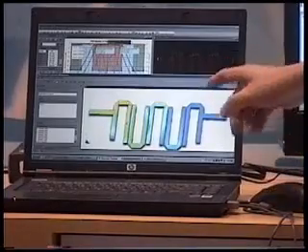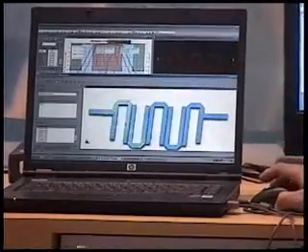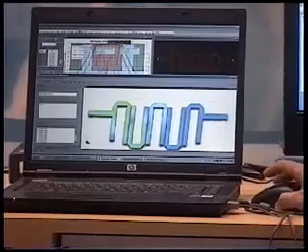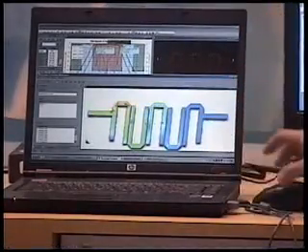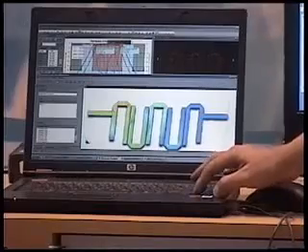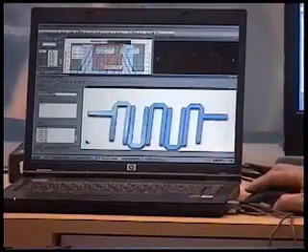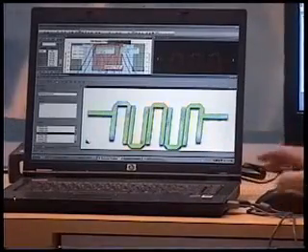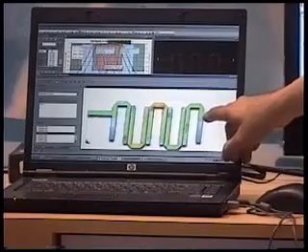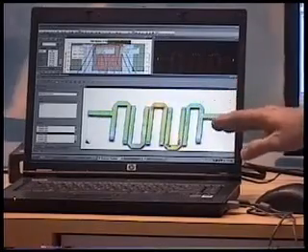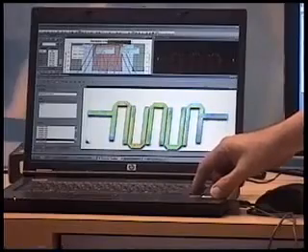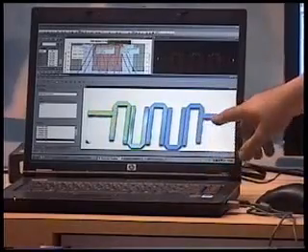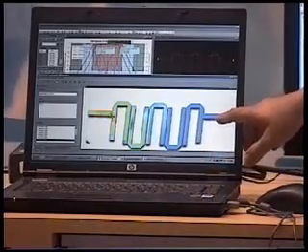Now what is interesting here is I'm showing the surface current flow in the stop band. In the lower stop band, you can see that there's no current flowing through here. And if I now scroll through, this is the current flow in the pass band of the filter. And if I scroll up the current to the upper stop band, again, the current does not flow.